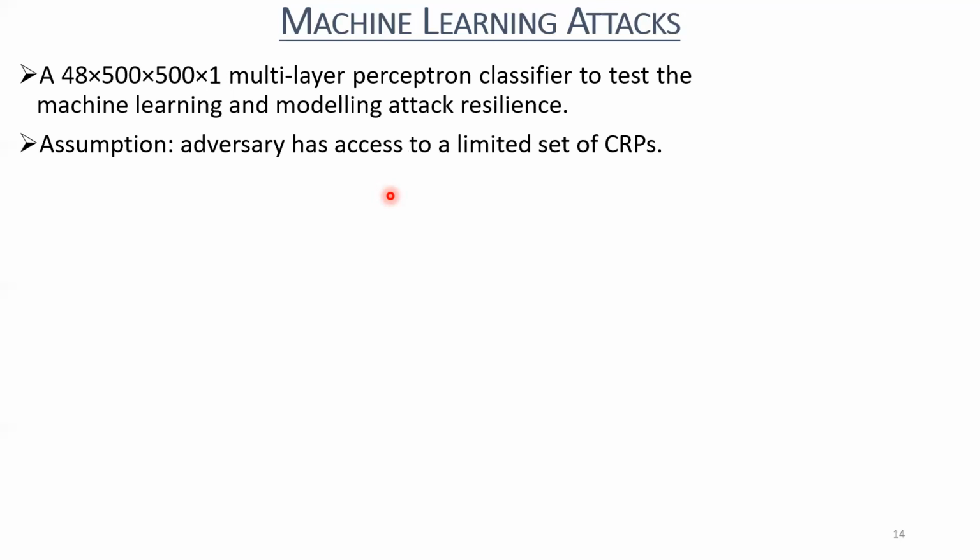I assumed that, since I am the adversary and have access to the channel through which the raw challenge response pairs are communicated, I will have access to a limited amount of CRPs. The number of CRPs is huge because the number of such bit strings is large. In a NAND flash array, the page size is 1024 and you have 16,384 such strings in each page.